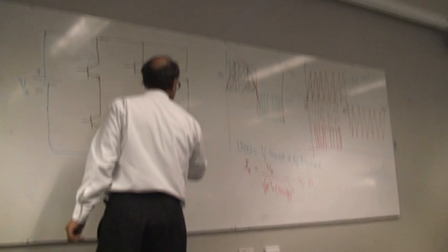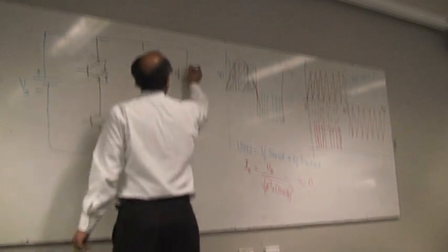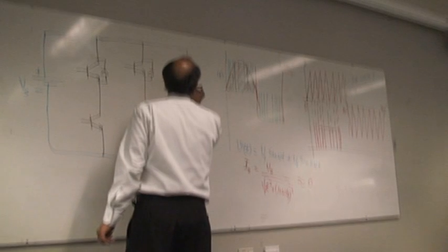So these are my 3 sets of legs. They are all semiconductor switches based on IGBT. Everybody has a parallel anti-parallel diode, no exception, because it provides the path for the reverse current.